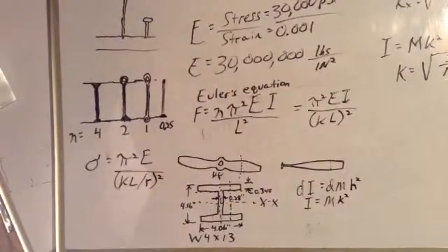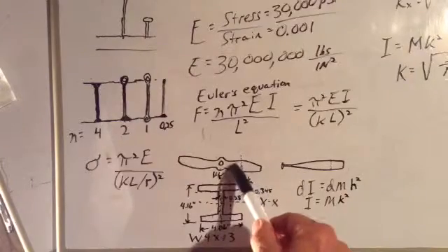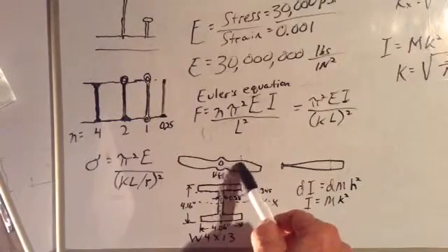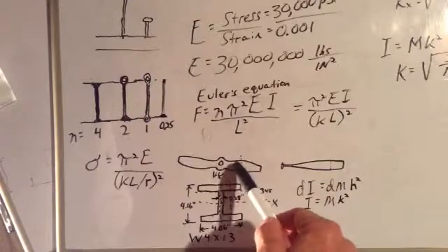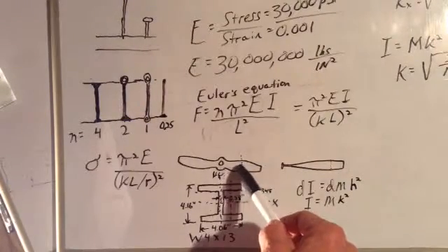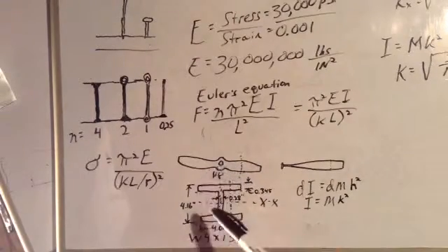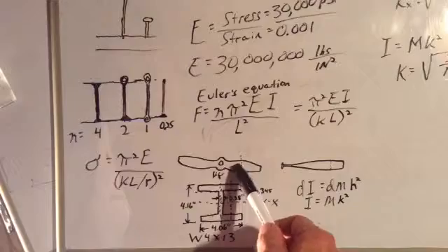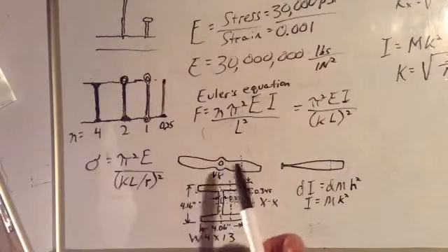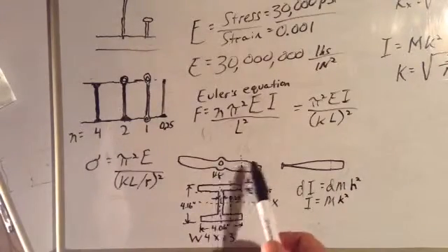Just as we have both area moment of inertia and mass moment of inertia, we also have area radius of gyration and mass radius of gyration. Mass moment of inertia is typically in units of kilogram meter squared. We're taking all these little increments of mass, which are going to be micrograms, but we use kilograms. That's what they eventually add up to. But all these little grams times the square of their distances is going to give us something like gram centimeter squared, or kilogram meter squared.